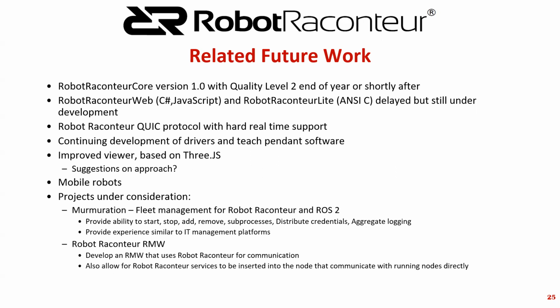Now, there's also Robot Raconteur Quick, which is using the new QUIC protocol, the new standard for web browsers and everything else on the internet. Again, that's a discussion for another time. Then there's continuing development of drivers, the Teach Pendant, and an improved viewer based on 3JS. This is what I've been using for the viewer, and Tesseract for the Python side. This is mainly intended for use with the Teach Pendant, which is web-based. I'd be interested in suggestions on that. I know there is some older ROS-based 3JS stuff, but I wasn't really seeing it maintained.